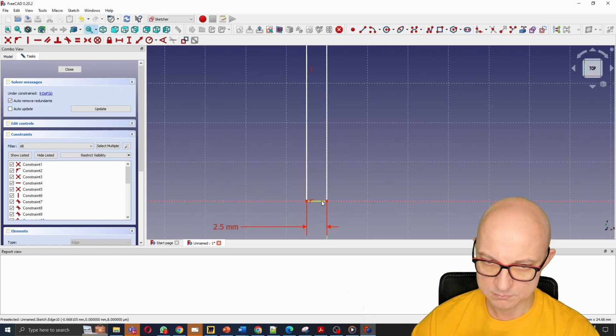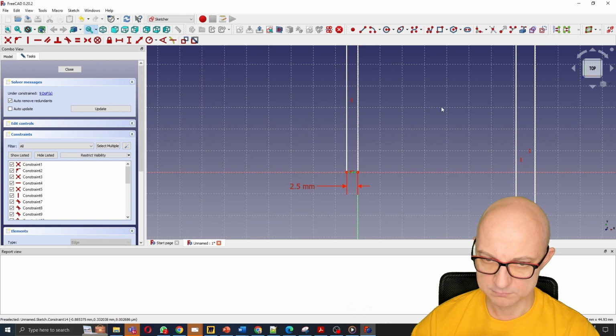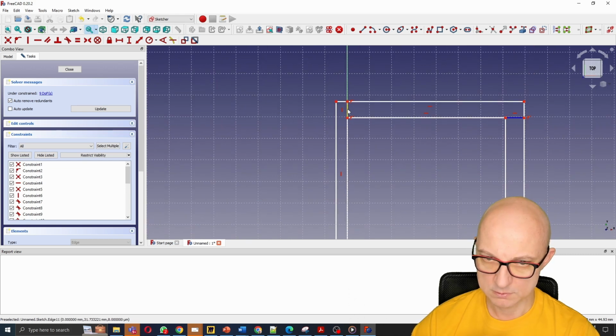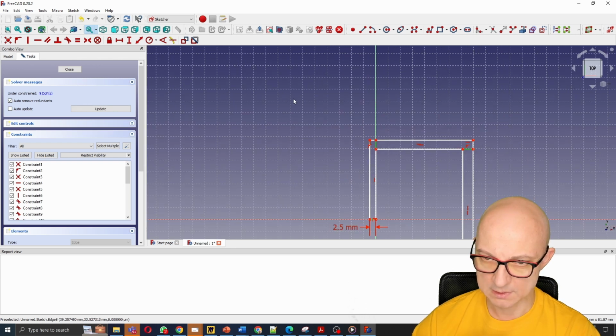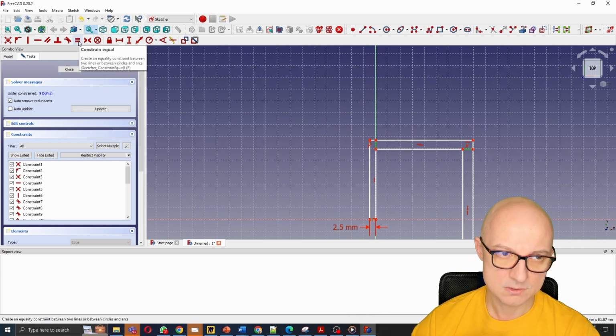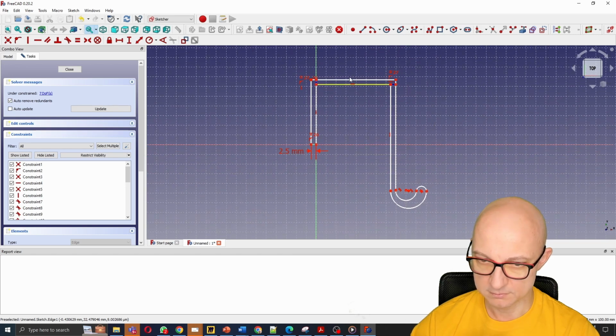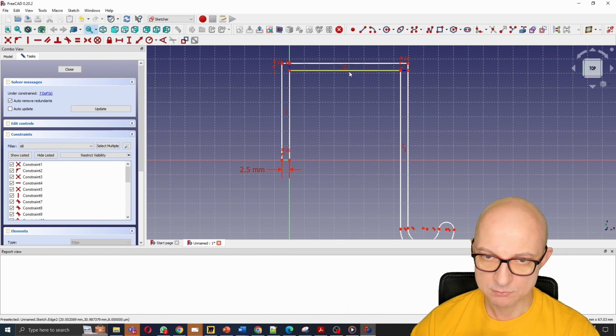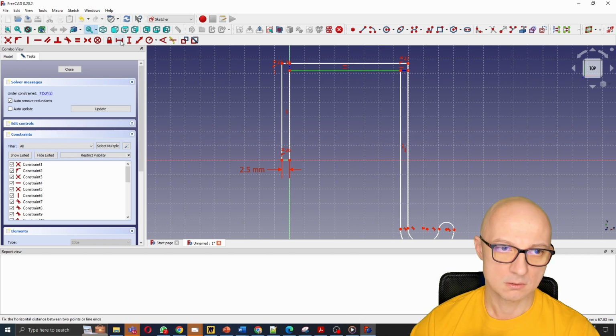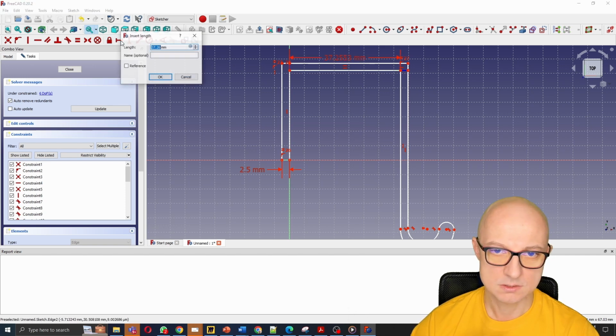And now we need to zoom in a bit. We select our first line, with control second and third. We have 3 lines selected. And here we say constrain it to be equal, or press E. Ding! And magic happened. So we see that this size is now the same, right? We said that this is the width of our doors. So we make it 41 mils.